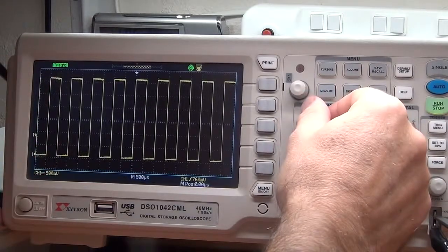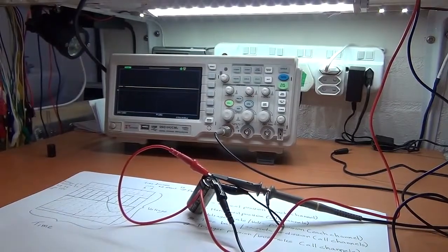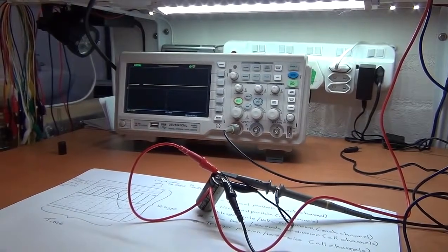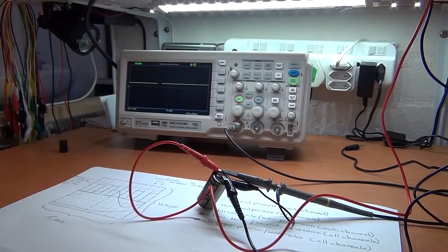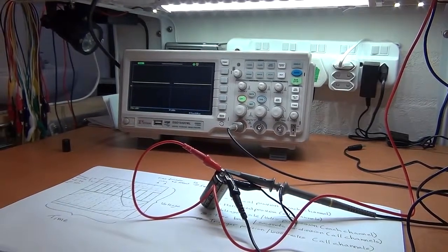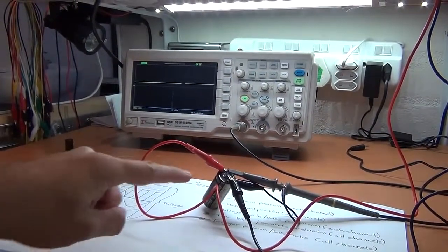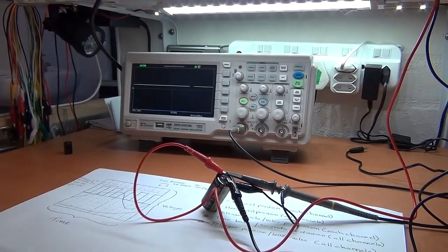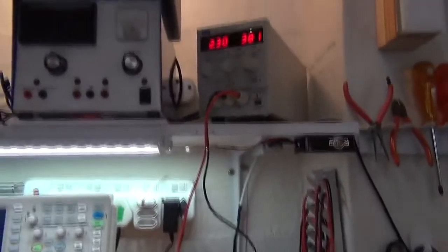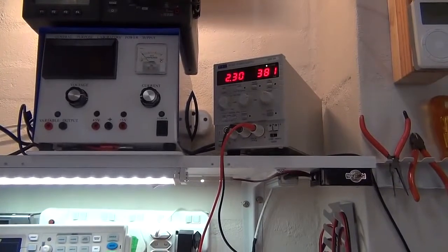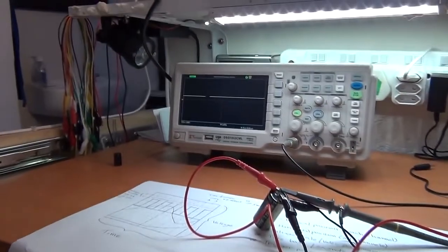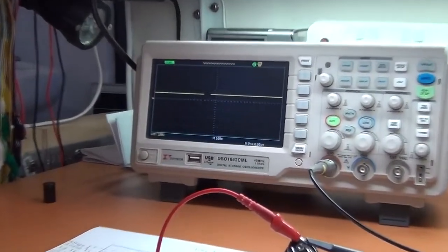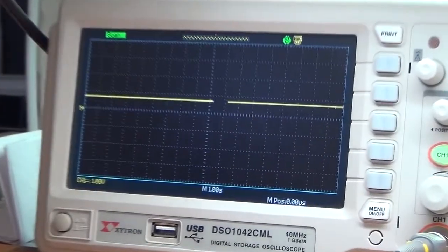that come into display. Right, so before we end this tutorial, I thought what I'd do is I'll quickly show you again one of the favorite things which I like using an oscilloscope for, and that's for showing a measurement over time of, let's say, something like a hybrid or supercapacitor being charged up. So I've got my variable power supply set with a voltage and a current setting, which I'm going to apply to the capacitor, and I want to see over time what that build-up is like.